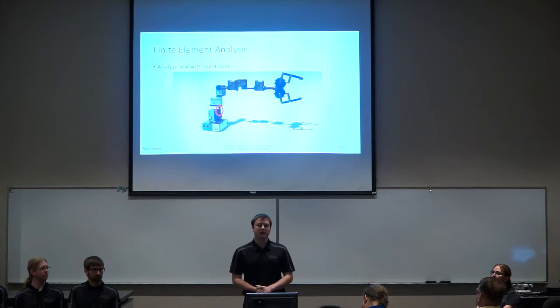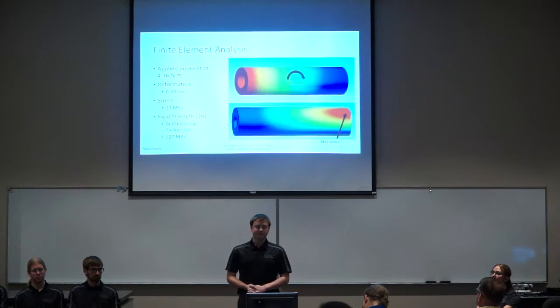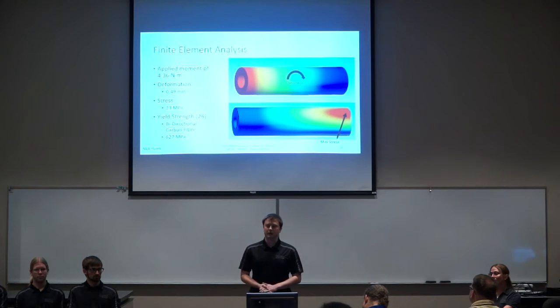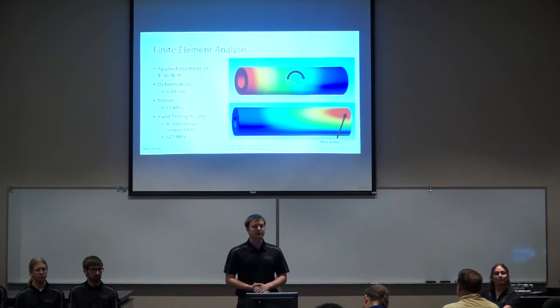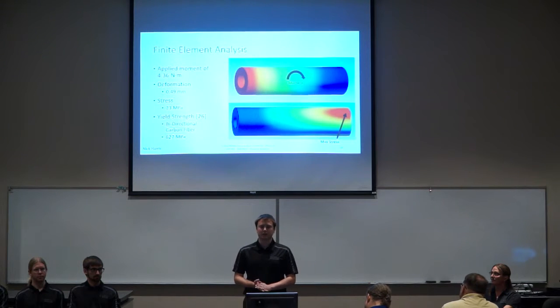And next, we also analyzed one of the links. You can see that circled in red there. Again, we applied the 4.36 Newton meters moment on it. And this time we achieved a deformation of 0.49 millimeters, so it's a little bit bigger. Still not too terrible for us.